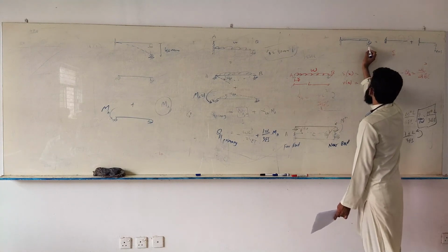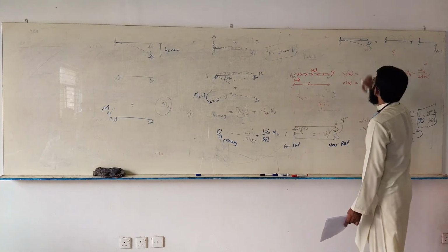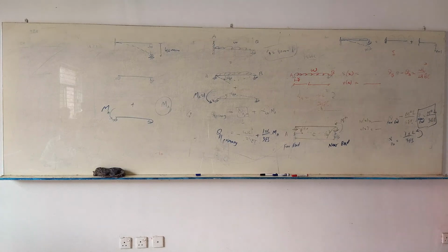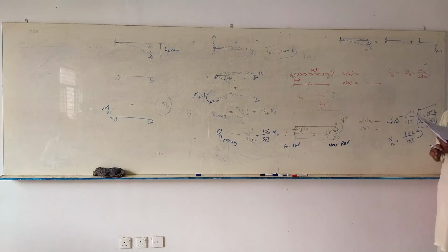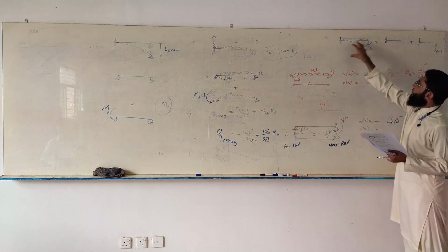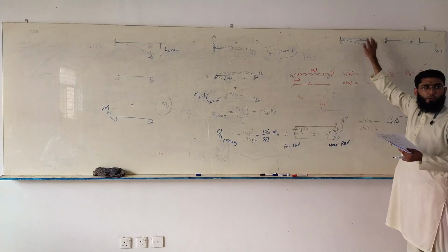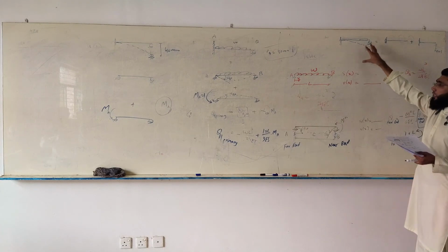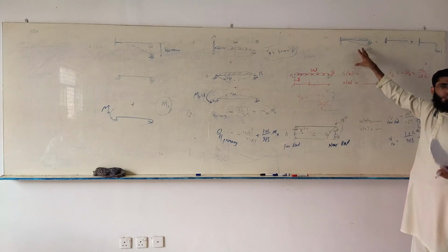So, can you imagine what's happening over here? The two displacement profiles that will be generated. So this is one displacement. This is the displacement profile of an actual structure. If this is 0, displacement is 0, it remains straight. It remains straight, no deflection, no rotation anywhere. But if this is the situation, we have a settlement at this end. So this is the displacement profile of the given structure.